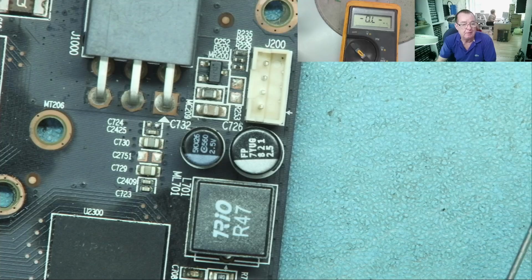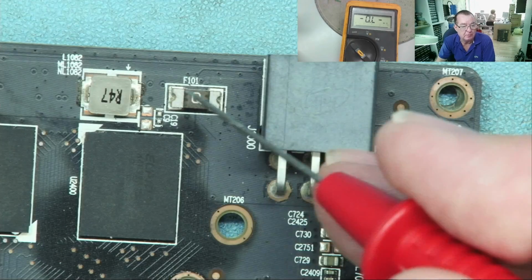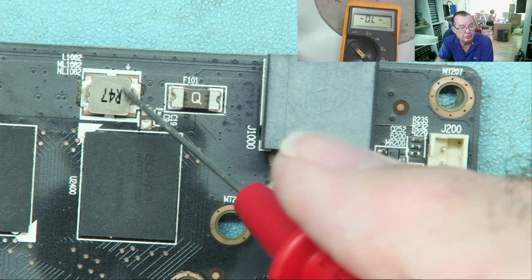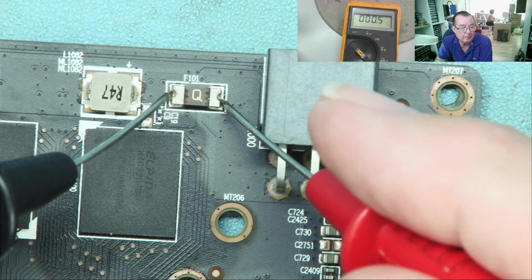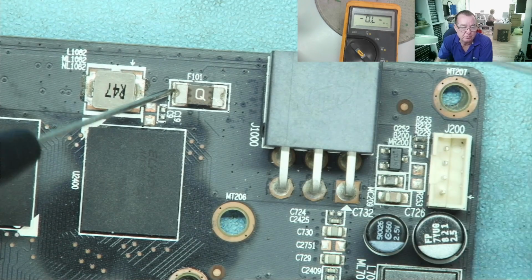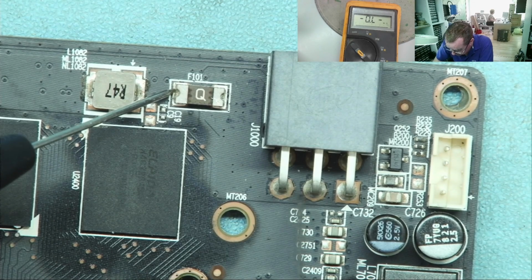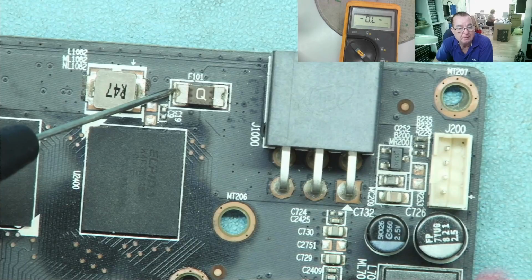While we're on here, let's look for any more fuses. If there are any, they're going to be up here. Yeah, there's one there. And there's another coil, by the way. That reads 0, so we know the fuse is intact, so that's another good one. That will come from the 12 volts. Yeah, which is here, okay?